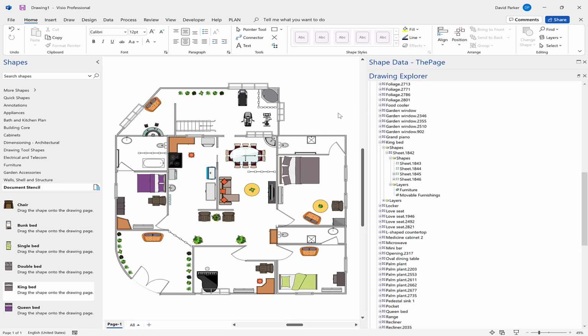Then I've got two masters, and I haven't got the ability to control them nicely. So switch on Match Master by Name on Drop, and even if you pull it from the original stencil, it will find that master by name and only use the one that you modified locally. Okay, so what's the advantage of that?